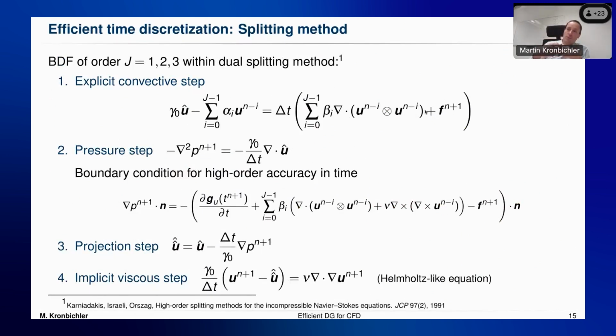So this is not a classical pressure correction, the Chorin type method, this is using the momentum equation in the first equation as well. In that case, you would actually see a first order accurate method. But this particular splitting, where you do the pressure between the convective term and viscous terms, is actually a higher order accurate splitting. So in this case, it's not so bad.